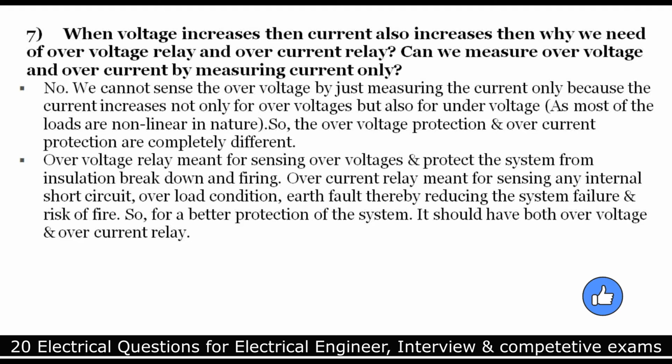No, we cannot sense the over voltage by just measuring the current only, because the current increases not only for over voltages but also for under voltage, as most of the loads are non-linear in nature. So the over voltage protection and over current protection are completely different.